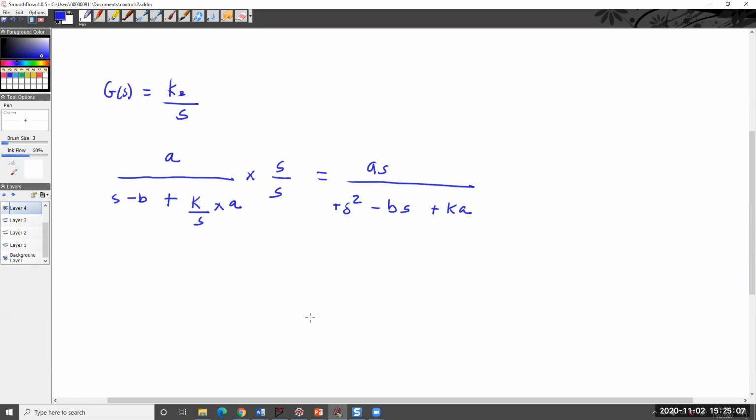And the best answer would be to use the simplest kind of feedback. You can do proportional just with a ratio of 2 resistors. If you wanted to do a derivative, you'd need another op-amp circuit or something taking the derivative in the feedback path.